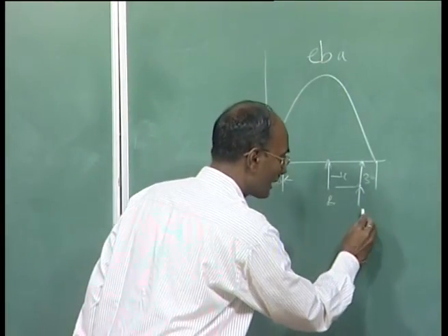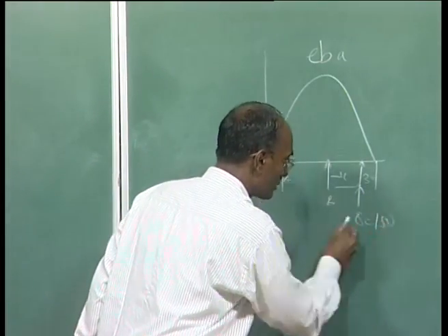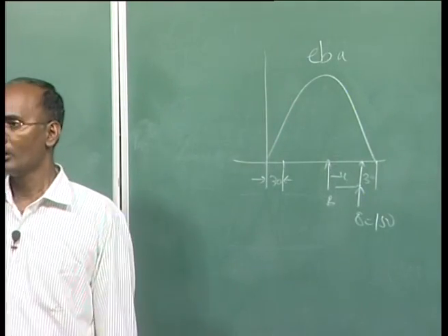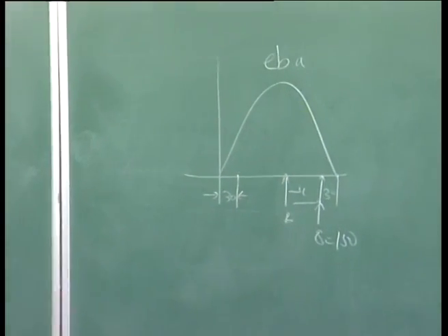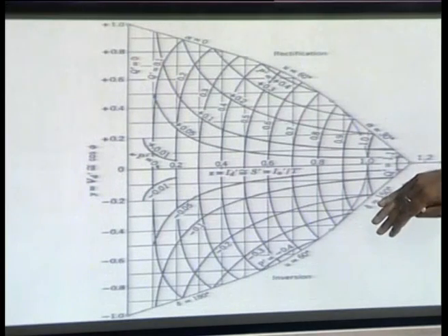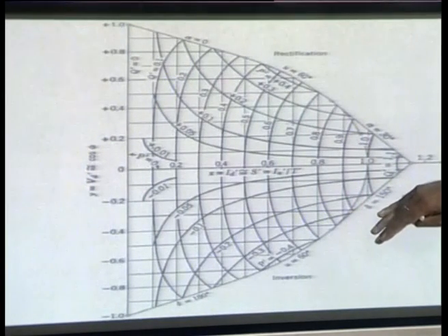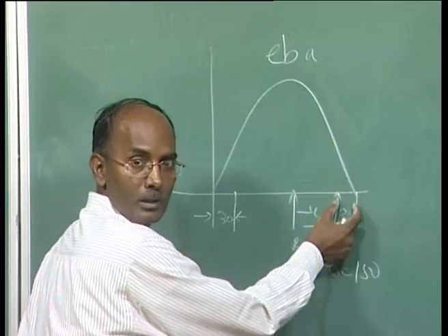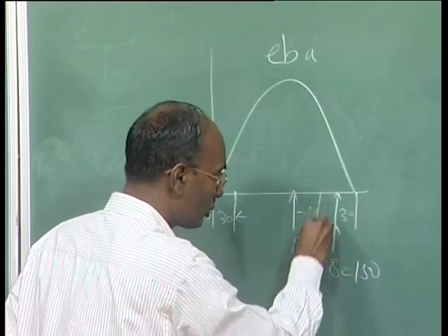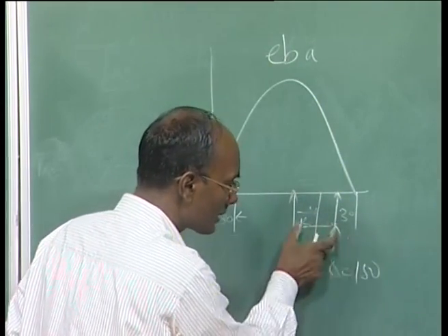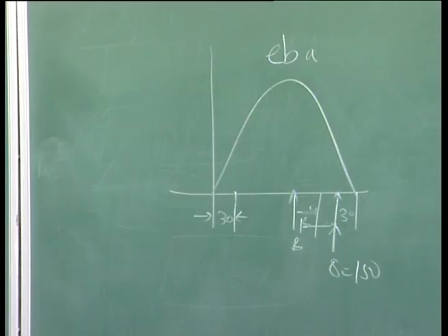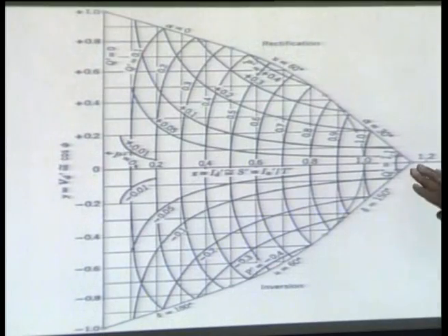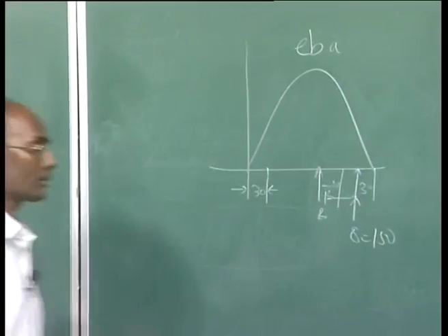So this delta is basically 150 degree, meaning alpha plus beta. In this case this is alpha 30, here it is not alpha 150 degree, it is delta 150 degree, because we are concerned with where it is going to change. So it is your beta, then there will be U degree, so beta plus U is basically your delta. The concern here is 30 degree, meaning 180 minus 150 degree. Now let us draw the AC side quantities.